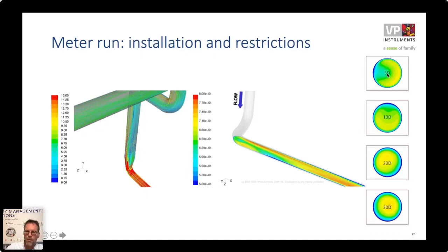And if you would install a flow meter in that, and basically it calculates the average velocity from that spot velocity in the middle. So if you would mount it very close to a source of distortion, in this example it's an elbow, and you would mount it here at say 5 diameters away from the elbow, so that's about here, then the air profile, the flow profile is not very symmetric. So the flow sensor will show maybe a lower value, sometimes a higher value than the average flow. And that effect can really be dramatic.